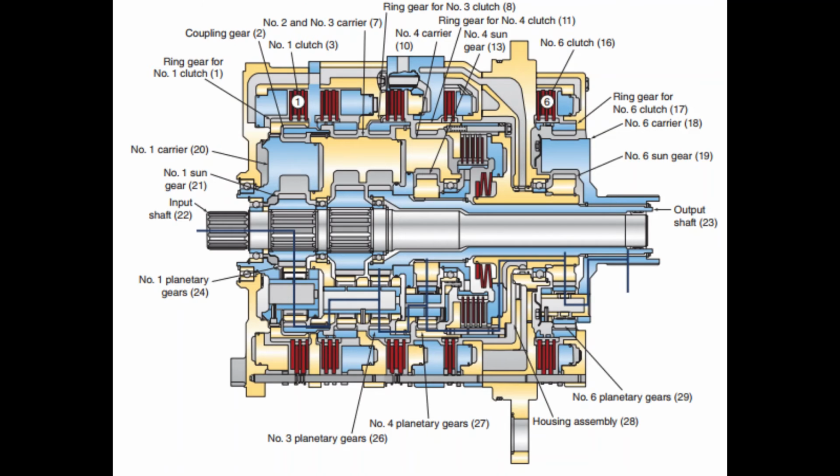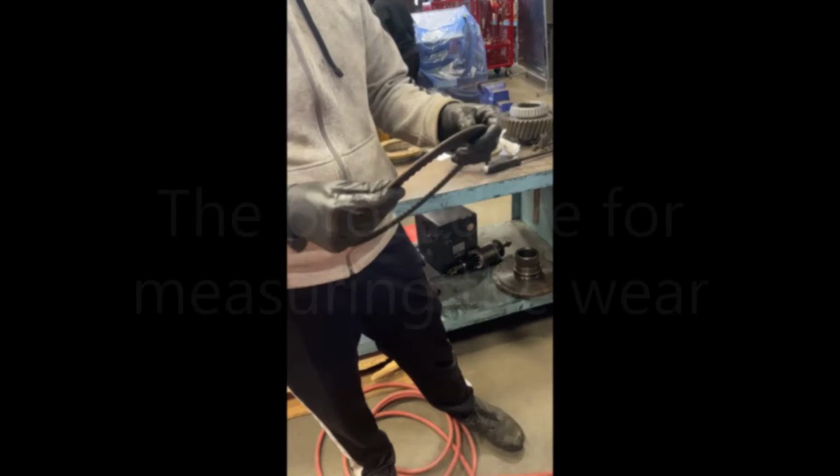Number 3 and 4 sun gears are held at the same speed of the output shaft. Number 4 ring gear 13 is output, planetary carrier is the output through the output shaft. Output shaft and number 5 carrier 18 are splined together and rotate at equal speeds. As a result, a multiple reduction output is divided between 3, 4, and 5 planetary gear sets.